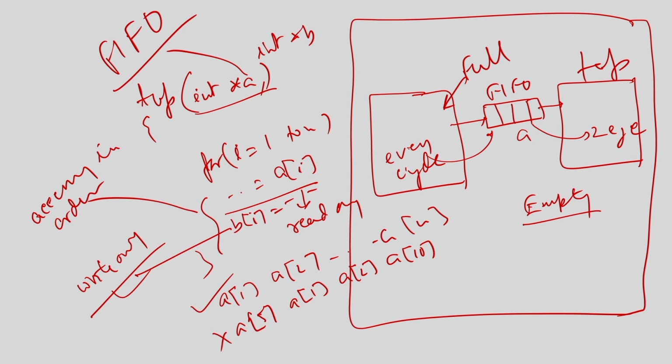So whenever the access is read only or write only and in order, not random, it is converted into a FIFO, and producer and consumer can run asynchronously, synchronized by blocking read and wait on full. This is how it can be done.